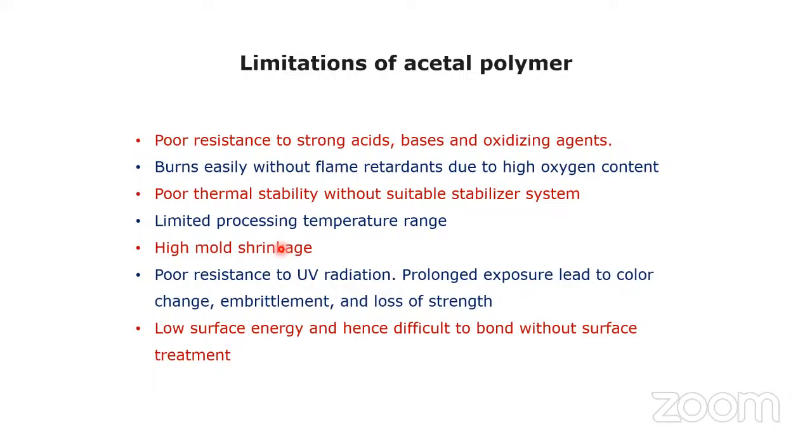In a mold, because here I have mentioned high mold shrinkage. In a mold I am talking about, correct? During cooling, your molten polymeric material is already filled in your mold, but it will take time to get arranged in a crystalline way. When it arranges its crystalline nature in the cooling process, it will create some vacant space in your mold. That is nothing but your shrinkage. Is it correct? Yeah, that's correct.